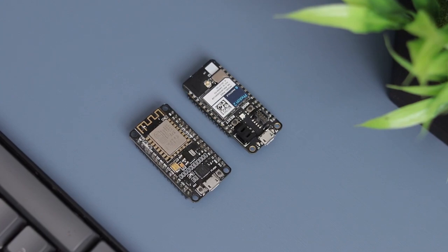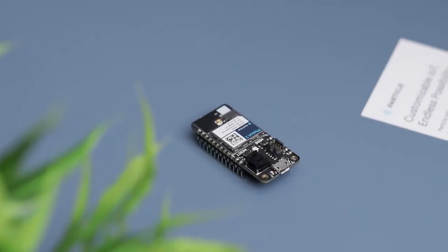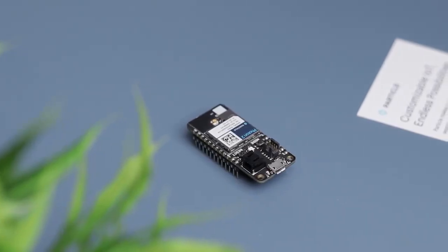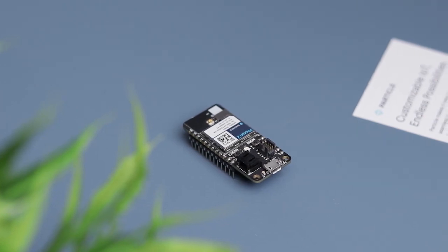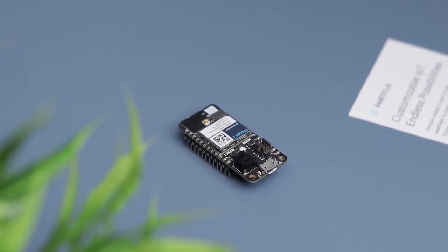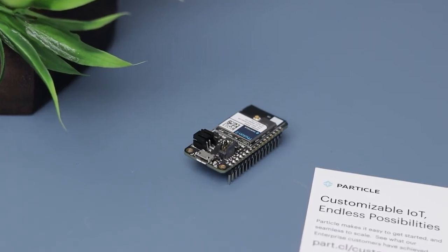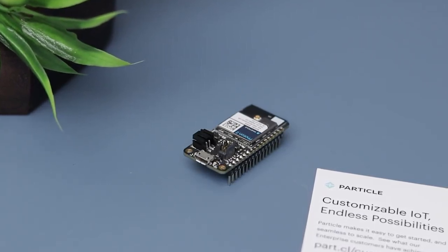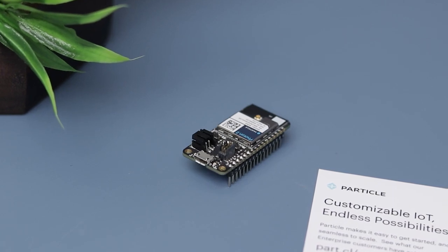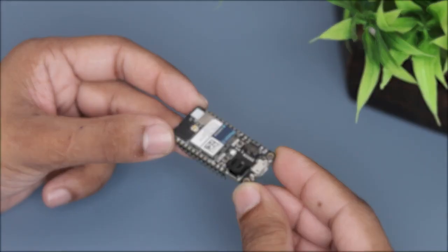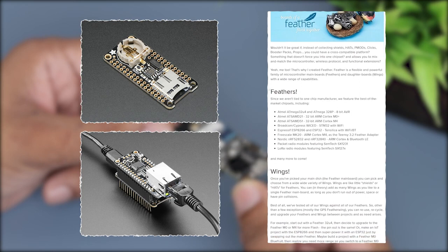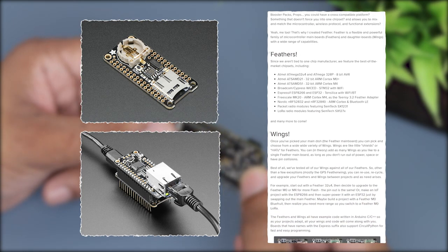The Photon 2 supports Wi-Fi 2.4 and 5 GHz, Bluetooth 5.0 and comes with much larger RAM and flash memory that can support larger applications. Talking about the CPU, it has a 200 MHz Cortex-M33, 3 MB of RAM and 2 MB of flash file system. It uses the Adafruit Feather form factor, and it is compatible with FeatherWings and other modules that use Adafruit